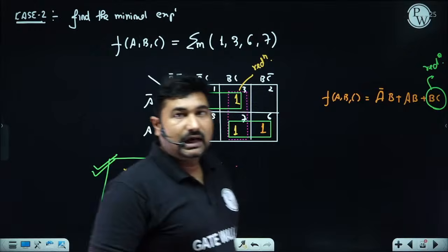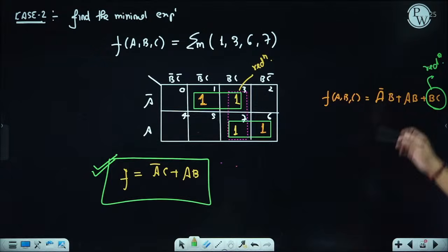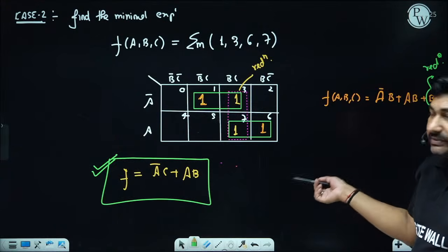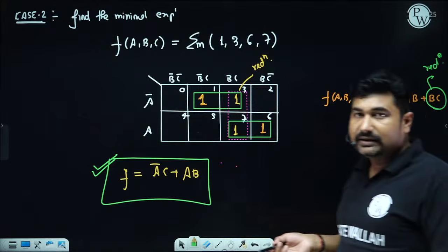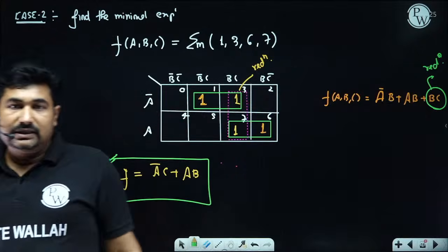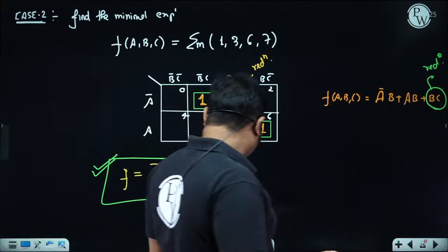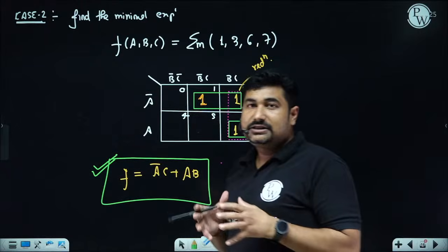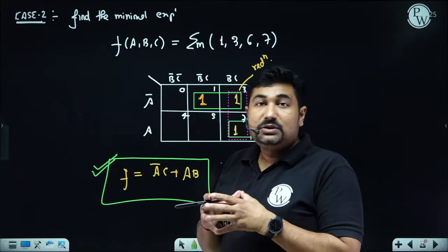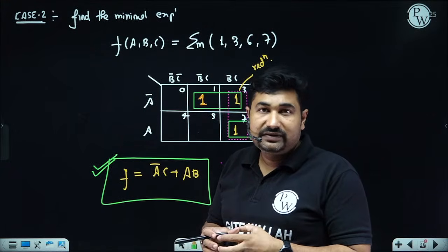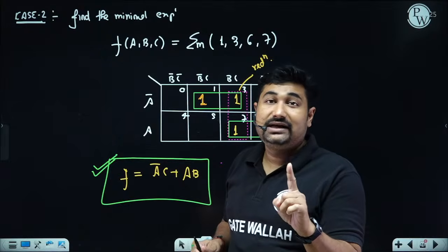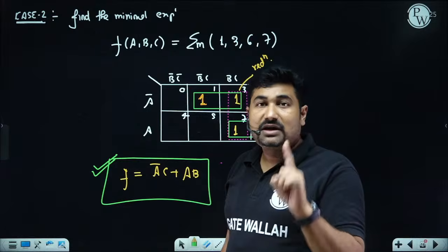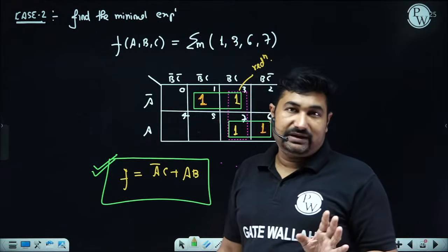Is it okay? How many of you are able to understand, Betaji? Instead of going with Boolean algebra, we have a Boolean algebra rule as well that shows a redundant term. Hoping all of you remember that. Is it okay? What is the essential prime implicant? Essential prime implicant is those groupings of logic level 1 which contain at least one min term which is not part of any other prime implicant.